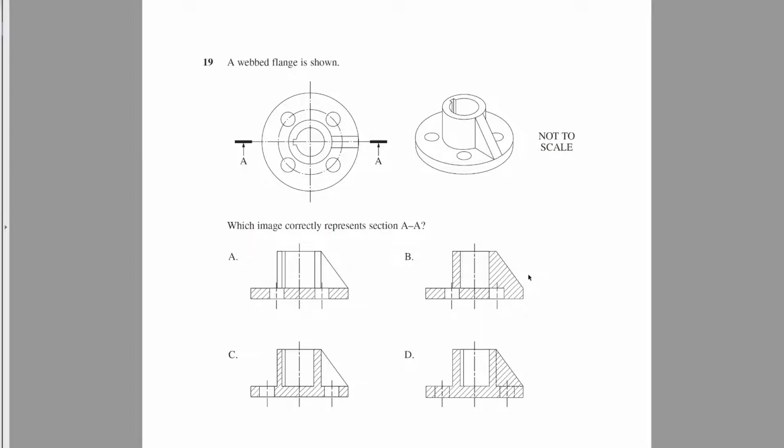excuse me, they're both wrong because the Australian standard effectively says that we should not. So this stiffener, right? It doesn't run for the full thickness, and if we section it using the same hatching, the manufacturer might think that that thing goes the entire thickness of the object, and if they do that, well, that's going to be misleading. So what we do in the HSE, we don't section stiffeners.